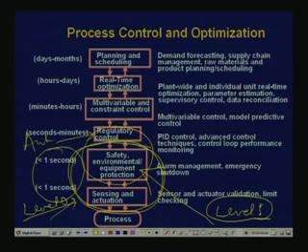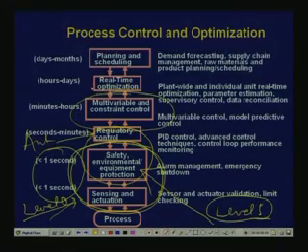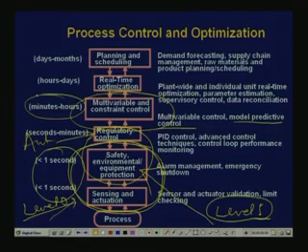and then, as we said, you need to give very good set points to these automatic PID loops. That is again computed by multivariable control models, where you consider the interaction among the various variables. You do what is known as model predictive control. It is a very modern technology which is used in a number of process plants. Here you are talking about giving set points which hold typically over minutes, hours kind of horizons, and then you have